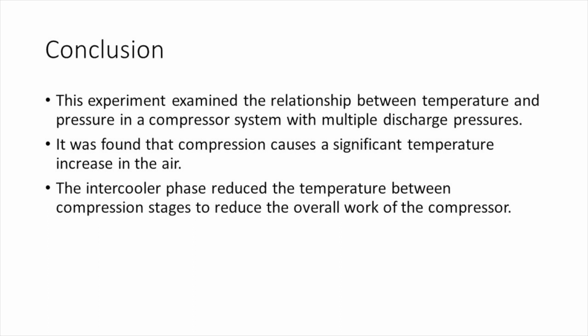Since compression is an adiabatic process, we have an intercooler that mimics an isothermal process, which makes the gas much easier to compress, and therefore we can achieve a much higher compression ratio.